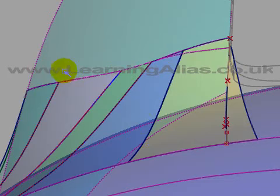The curve I projected onto this C-pillar primary surface in F6 came along here. So this is the curve here, and it came along here. So that would have given me a patch this shape, but I know from experience that that's not going to build a good CV structure for this, let's say, stressed patch.